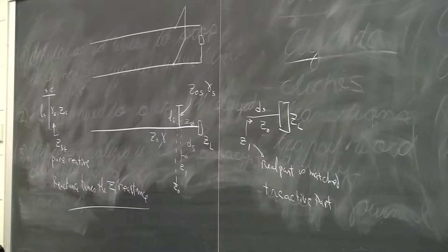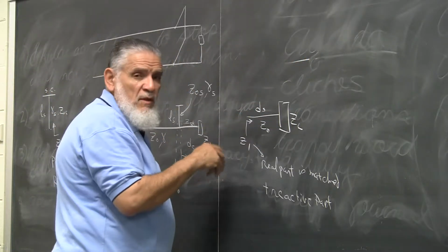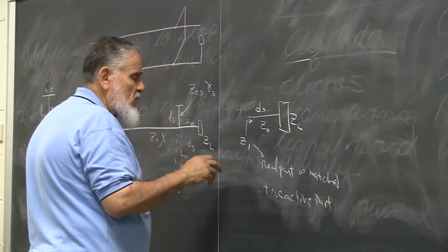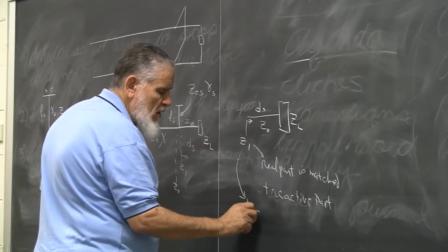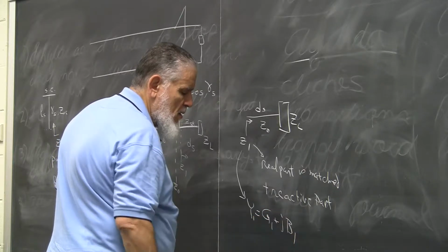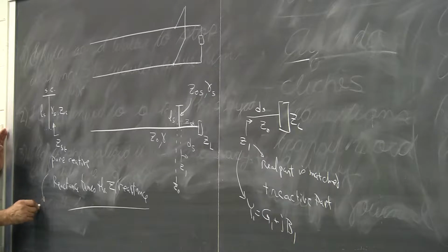So in the Smith chart, if the shunt, that means we work with admittances, right? We said that last time. It's best to work with admittances, so instead of Z1 I work with Y1. It's equal to G1 plus jB1. And obviously in that regard, this has to be a minus jB1.